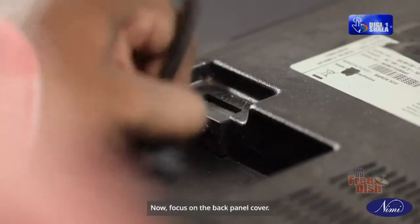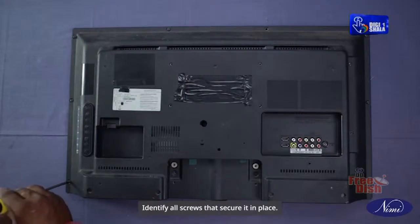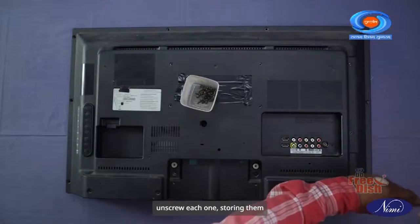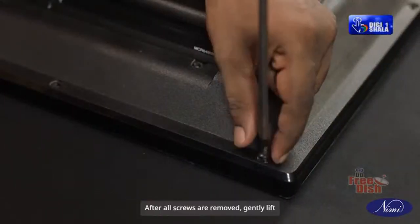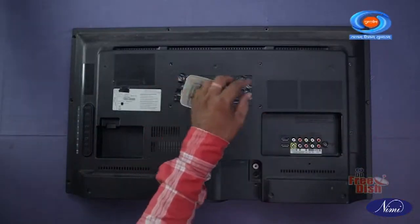Now focus on the back panel cover. Identify all screws that secure it in place. With a suitable screwdriver, methodically unscrew each one, storing them safely for later reassembly. After all screws are removed, gently lift the back panel cover away.